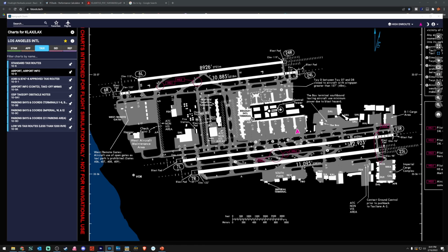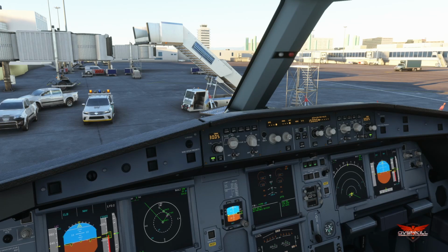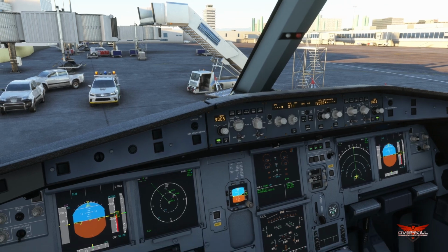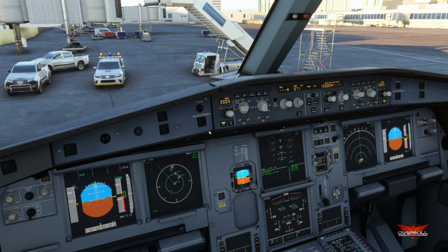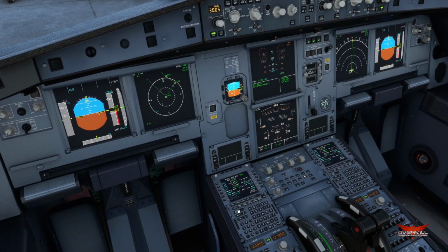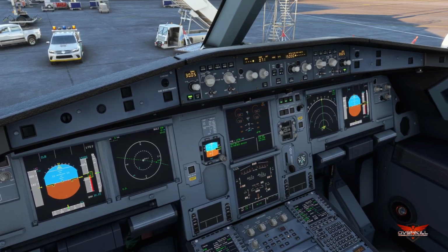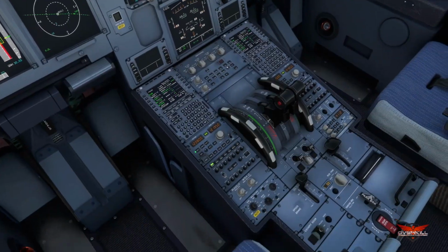So again, turning that display capture off. We're going to go to our heading mode and find, let's go, which way did I go? Okay, there we go. That's what I wanted. Now we're going to tune it to 071. There we go. So now we also have our final runway heading set for takeoff. Flight directors are set. Constraints are selected. We have our display view. I like to keep it in close until we are clear of the departure. Let's return to the flight plan page on the MCDU. And I think we are ready to button up.